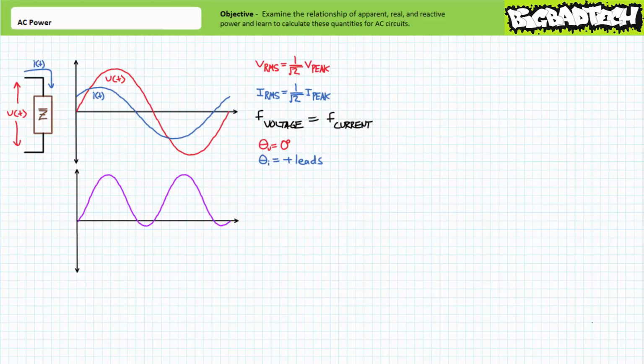First, given the power waveform is on both sides of the horizontal axis, there appear to be periods of both positive and negative power. Given positive power is defined as an element dissipating, absorbing, or consuming power, negative power is quite obviously the opposite, being occasions in which the element is supplying, returning, or providing power. This duality implies that the element in question is slightly reactive in nature, in that at times it consumes power from the source, and at other times returns it back to the source.